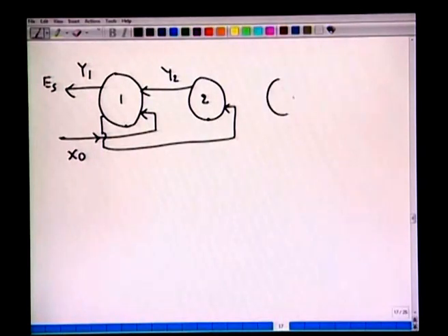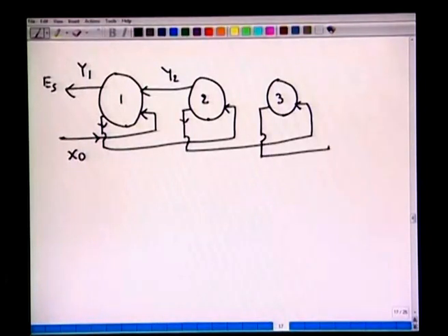Let's draw the third stage. So this is the stream which leaves from here like this, again it will enter like this, and so forth. The stream which comes out on the top, that extract phase, has a composition y3, and so forth. We have this composition, say y Np plus 1, which we drew here, and this is the composition of x Np.